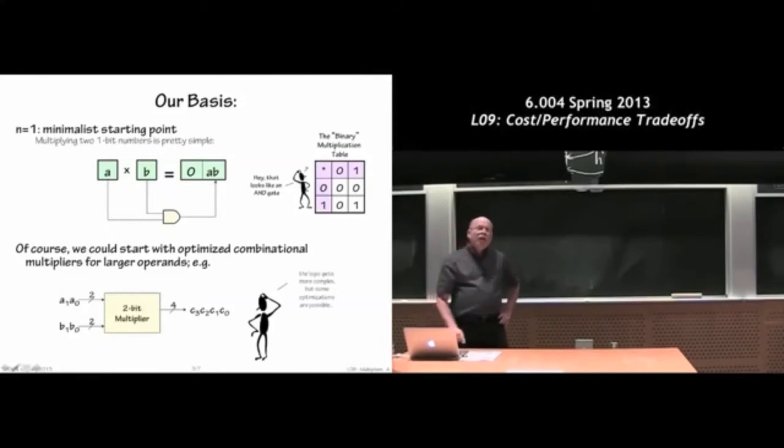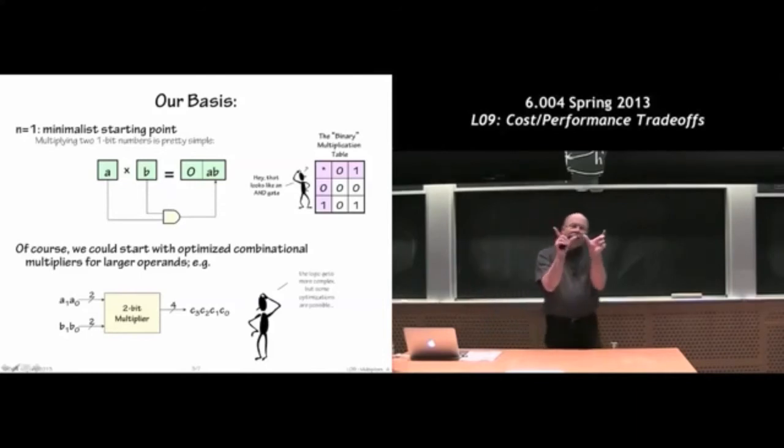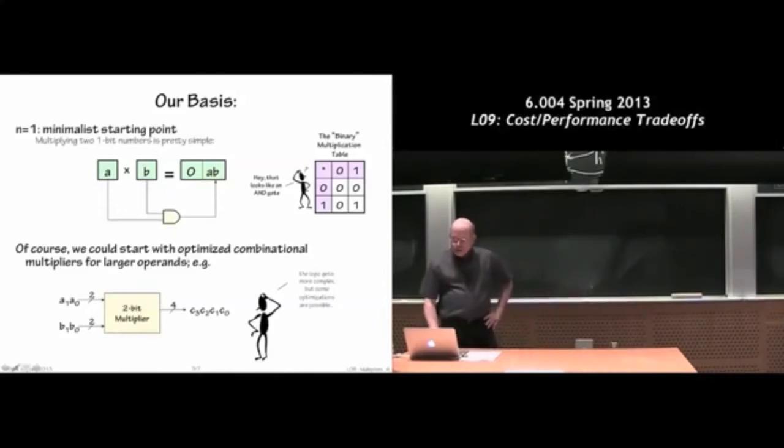But in general, when you multiply 2 operands of a certain size, you produce a result which is twice the size. The reason this little special case rears its head is because of the special properties of multiplication by 0. Multiplying by bigger numbers tends to produce 2n-bit results. We just don't happen to see that in this table.